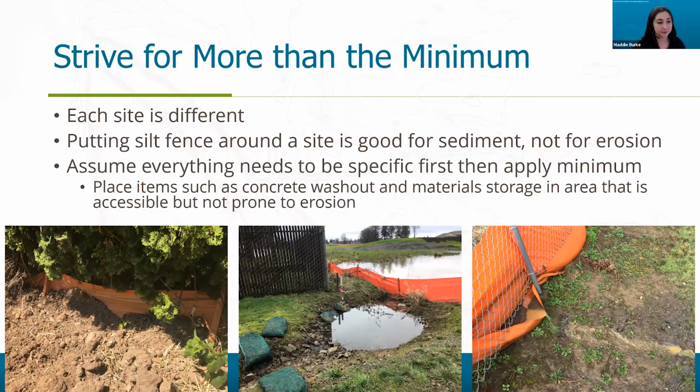So below I have some photos where silt fence was not enough. So in this first photo, you can see that the site has eroded and buried the silt fence. This is now failing. We in the city of Vancouver change out our silt fence once it's 1/3 full. So the site eroded over it and it's actually crossing over parts of it.